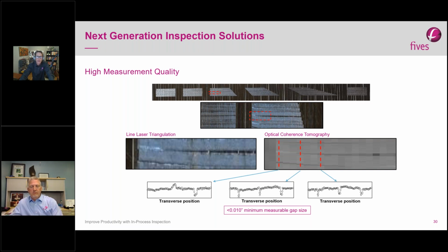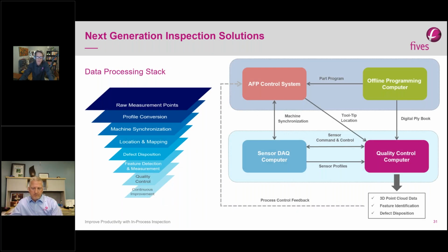And so you notice that this OCT produces a much clearer image and shows more clearly the transition from gap to overlap. And you also notice the number of points that we're taking in the last 3 images. We have a lot more measurements inside of the feature, right? We always want to look at how many points are inside of the feature because that defines how you can process that algorithm. As with many devices, everything has a limited deadband region, and that's where the feature goes to 0. So for OCT, that happens somewhere between 5 and 10 thousandths.